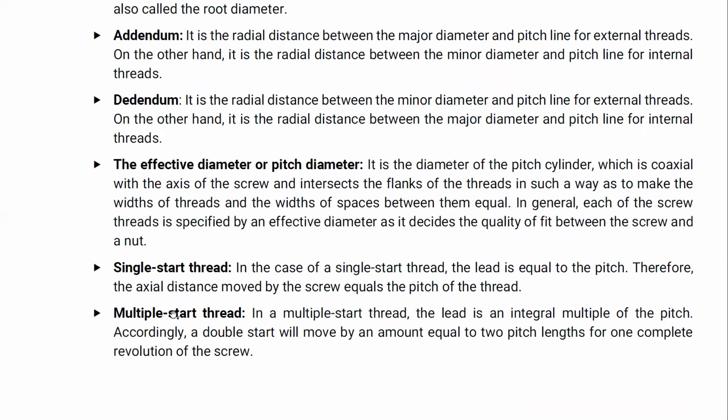Then single start and multi start. In case of single start, the lead is equal to the pitch, which means the axial distance moved by the screw is equal to the pitch of the thread. In multi-start, the lead is an integral multiple of the pitch. In double start, the screw will move by an amount equal to 2 times the pitch length for one complete revolution of the screw.